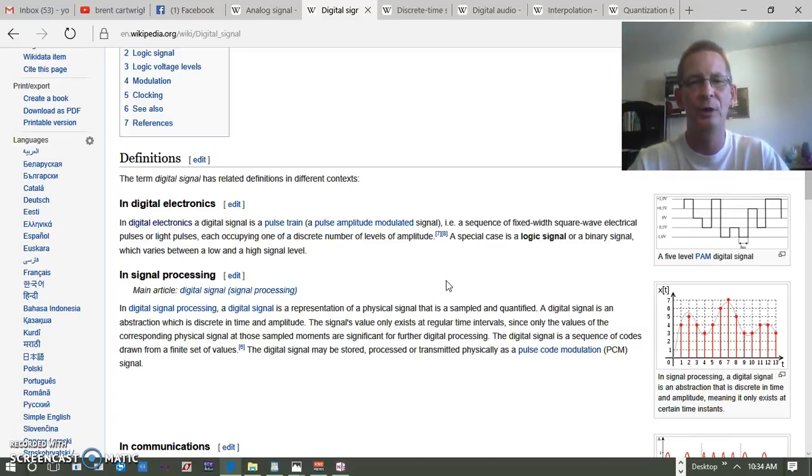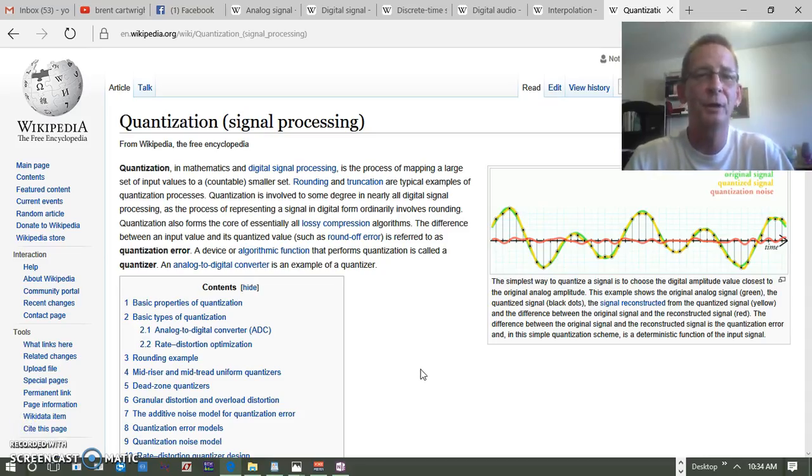And quantified, so, quantization. Let's take a real quick look at that. Quantization can be very complex, but let's look at this as simply as possible, and you can always branch out your knowledge. A simple understanding is that it's rounding and truncating. That means that for each one of these samples, quantization captures the sample and then rounds it to as close an approximation of the original analogous signal as possible, and truncates any information.